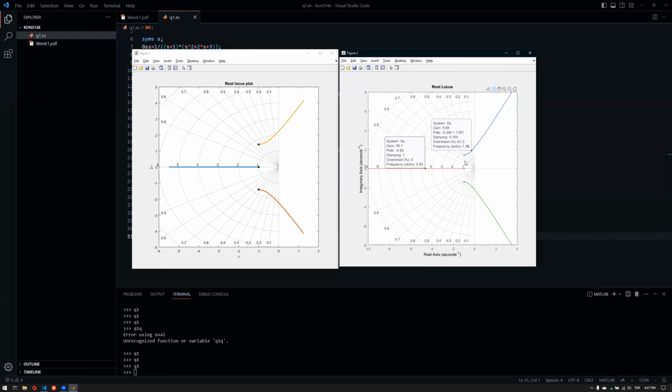If, of course, for this system we have a dominant pole placement, then we will talk about along this line. Something like that is along these lines, but we cannot conclude that. If the system is a second order system, then you're good to go. You can just use the overshoot value that is written on it, because there are only 2 poles. But other than that, for higher order systems, this Root-locus plot doesn't give you, and cannot give you, overshoot data here.